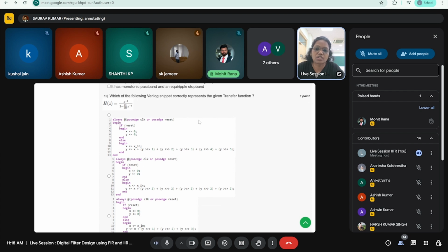That's what the question is about. If the coefficients, you can use in Verilog only the shift operators, right, to represent the coefficients. So very accurately 1 by 8 is okay. I mean, you can shift it 3 times. So how do we use the shift operators to represent the coefficients in Verilog? That's the question here.